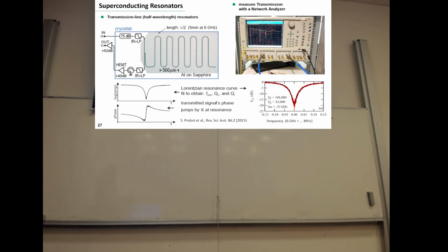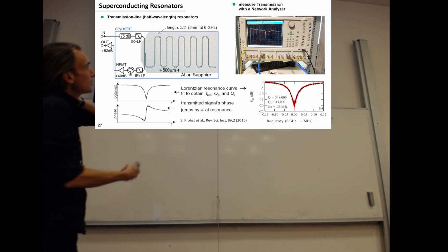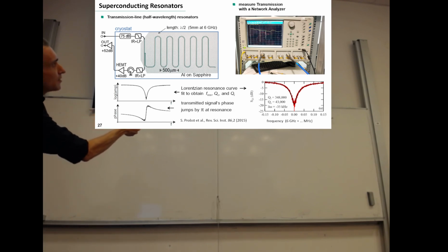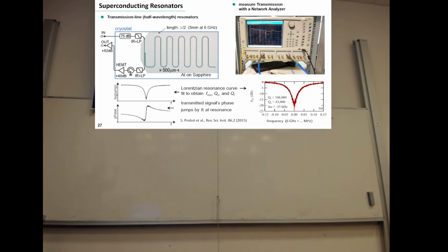This is the so-called network analyzer, a standard device to measure these transmissions of microwaves in this case. It's a very simple thing: you send microwaves at different frequencies, and it measures how much comes back. These two ports are connected to these 2 points here, and this is a typical result, with the amplitude plotted versus frequency. You see here already these 3 sharp dips, which are just 3 different resonators coupled over the same transmission line.